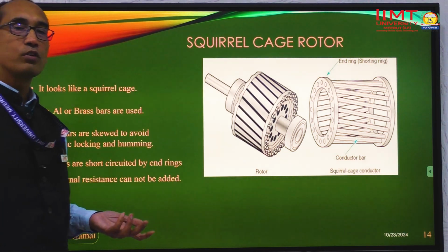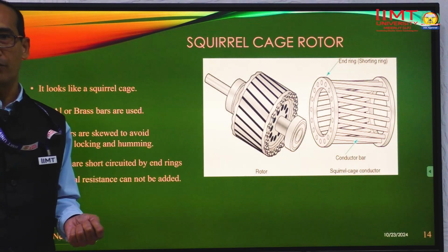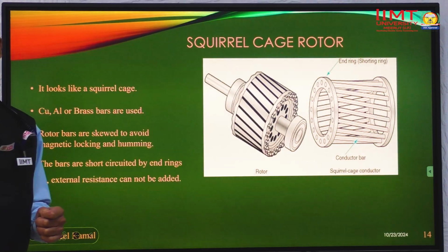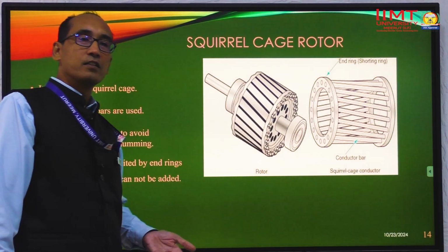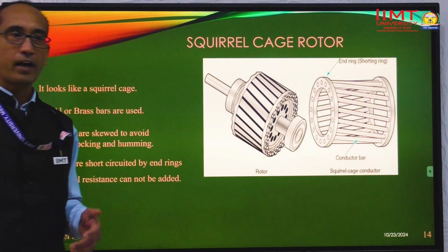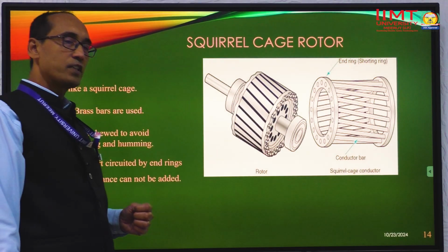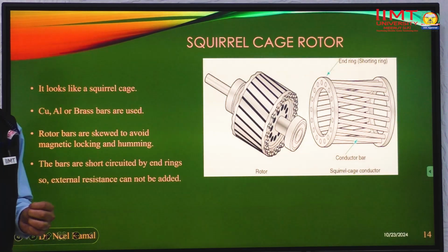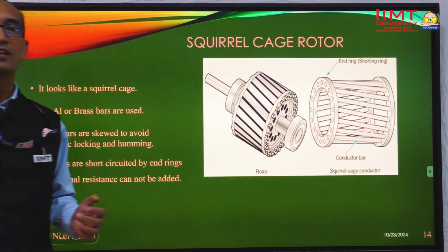So there will be no relative speed. No relative speed means no torque is developed now. In this case, the rotor speed again decreases, and whenever the speed decreases, there will again be a relative speed set up between them. So again it will recover the torque. In this way, we can say the three-phase induction motor always runs at a speed slightly lesser than the synchronous speed, but never attains the synchronous speed.